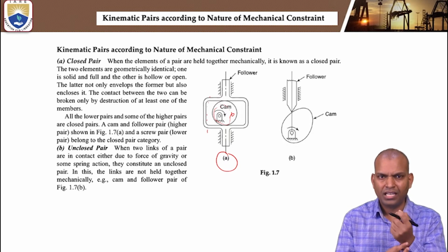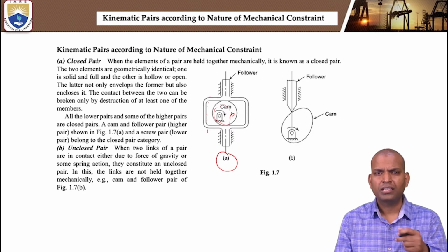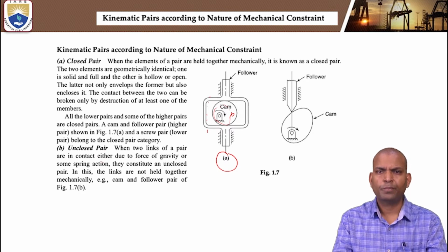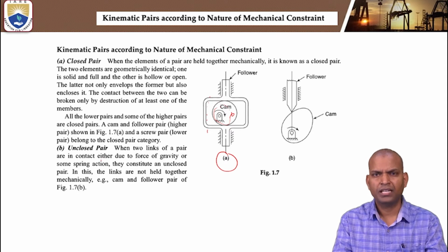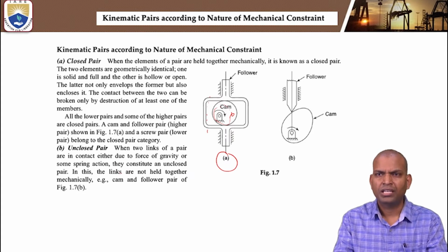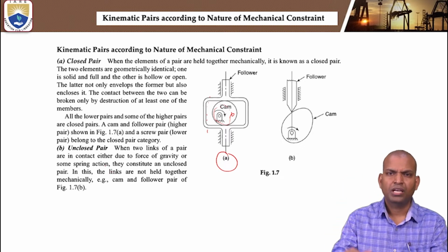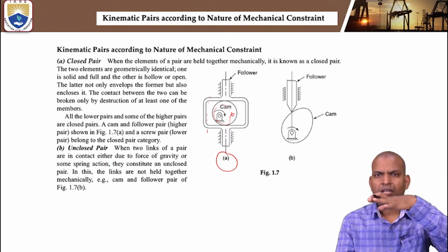But the contact can become either point contact or surface contact. We can also say that in this category, some of the lower pairs and some of the higher pairs can be considered. In this, the links are not held together mechanically, but by either gravity or spring, not by some external force, as we have studied.